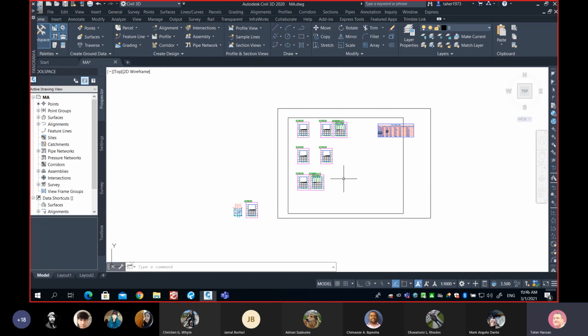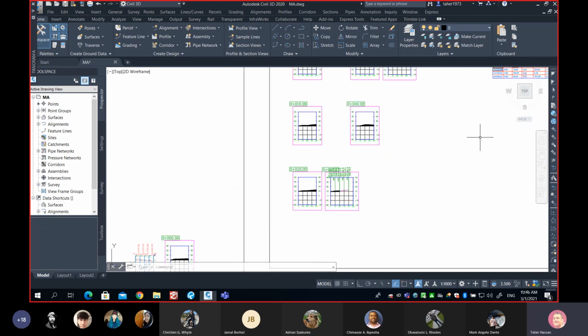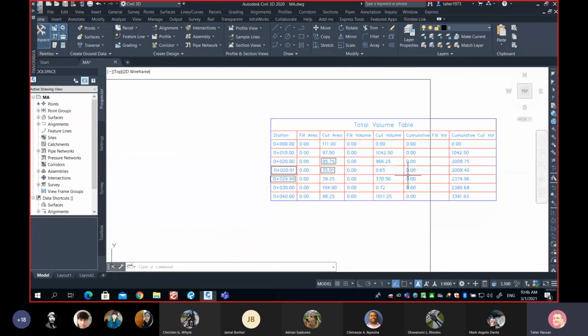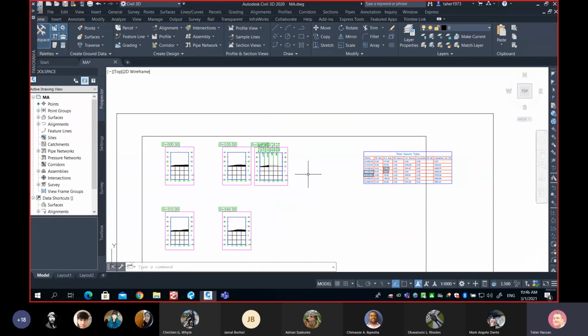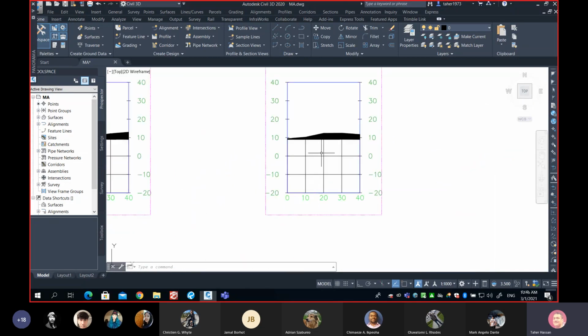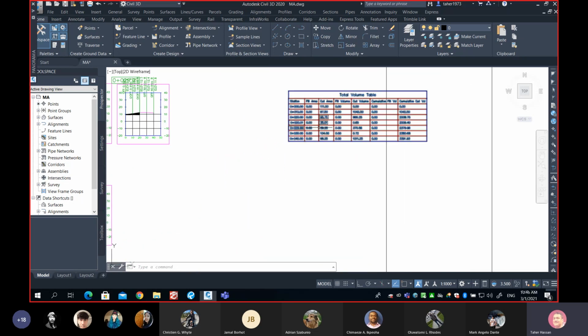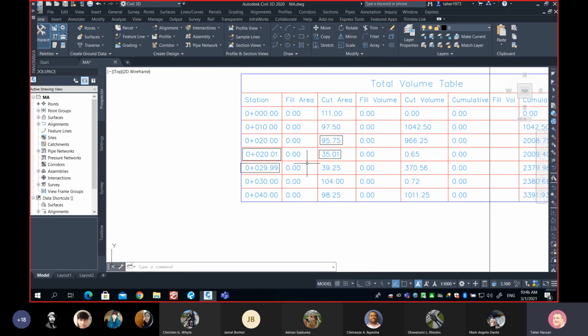How about the cross-section area method? It's a fantastic method. You can see I can give my client all the cross sections, all the areas, all the volume. So it's very detailed. You have evidence of your proof. And remember, those sections can be visually verified on site. If you go on site, you can simply verify those sections visually. So it's a very detailed method. However, it is sensitive to where you place your sections.